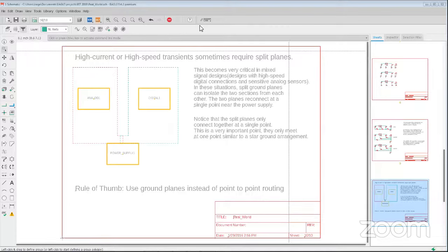With that said, the communication module is going to have its own filtering circuitry on it, so it's likely not an issue. If you have a good 4G communication module, which is what I'm assuming here, they've built in their own filtering to make sure that the power they're getting in is as clean as possible for their purposes. So your 3.6 volt rail is probably fine, unless you tell me otherwise. But keep that in mind: just because you put a linear regulator after a switching regulator doesn't mean your power is coming out clean. The ripple from the switching regulator is most likely coming in unaffected through the LDO.